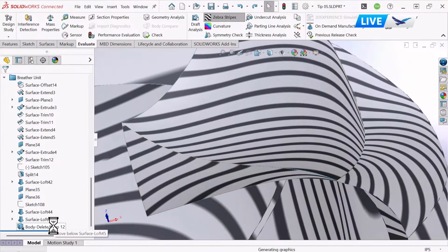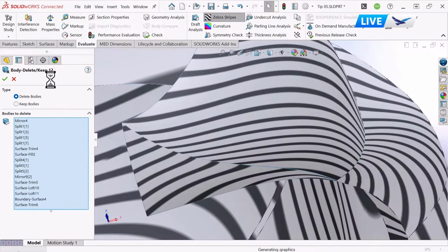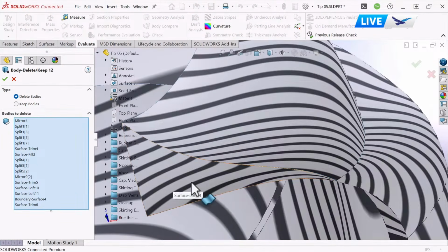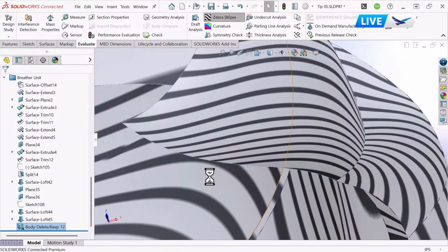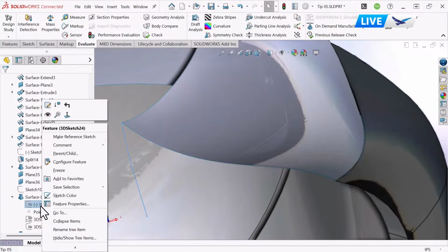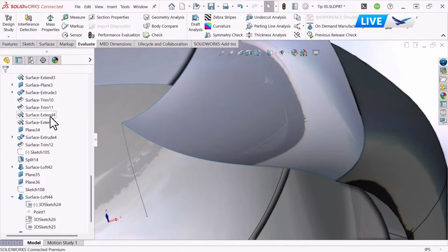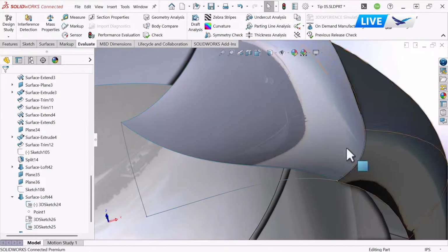So to do that, just that surface that I had lofted to, I'm going to delete it. Then use a surface fill. And with the surface fill, you can do the boundary edges. With the boundary edges, which you'll see in the video here in just a second, you can set to curvature. And on the edges that don't have any surfaces attached, that could just be nothing. But using the curvature of that loft, it will continue that curvature into that bounding surface. I'm sorry, the surface fill.